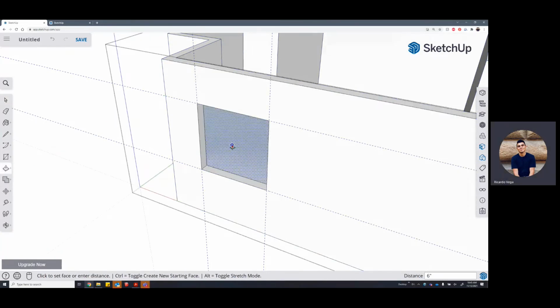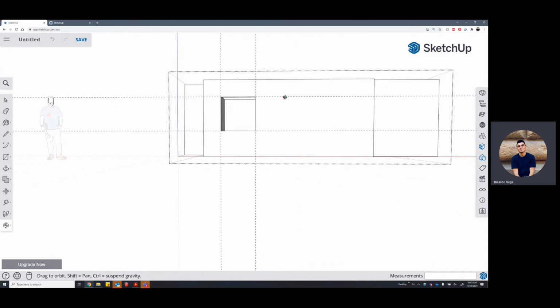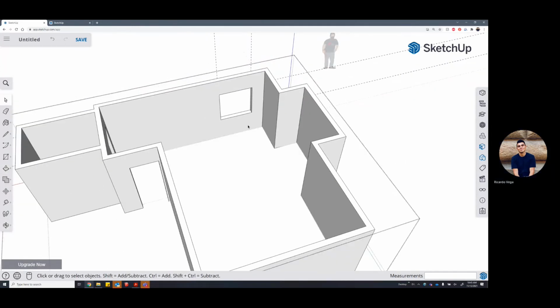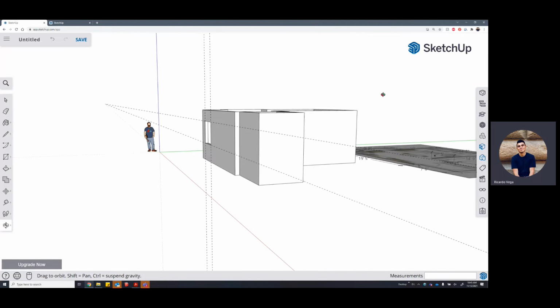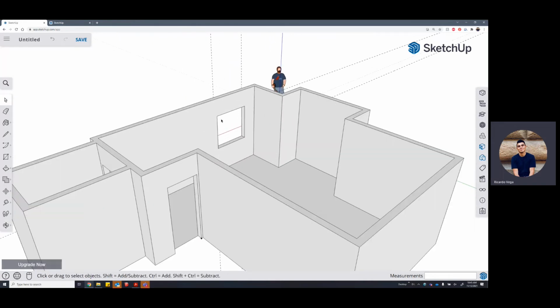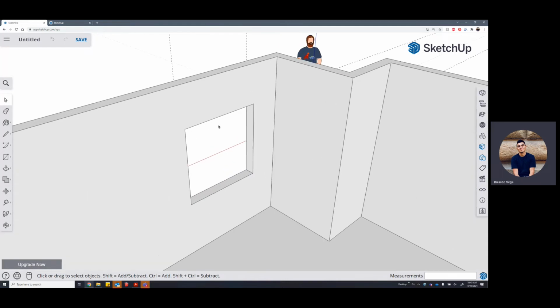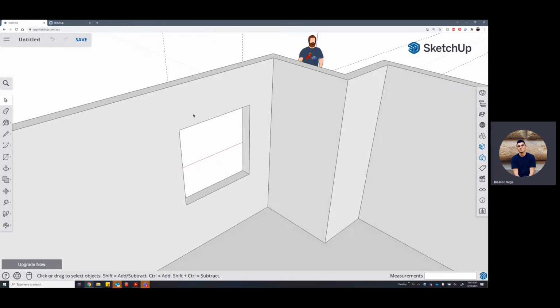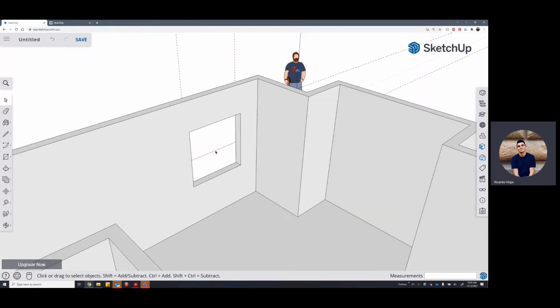So we could push that in, and if I push it, I can see the other side of the wall right there. It kind of clicks into it right there on the face, and if I click onto it, I've created an opening for my window, and you can see that I have that opening, right? Just much like a door. It's just that I did it backwards. This one I removed in the plan and I extruded it. This one I removed in the elevation and I pushed it out, like I deleted it.